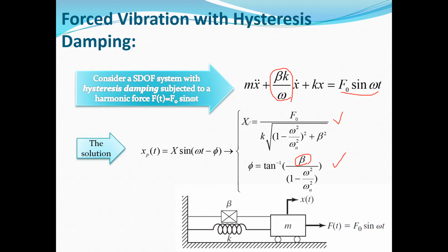So this is again an approximation, and we are using some initial assumptions. The first assumption in extracting the equivalent c was considering the harmonic response or harmonic excitation. Because we have harmonic excitation, we can use this approximation to find the response for this system.